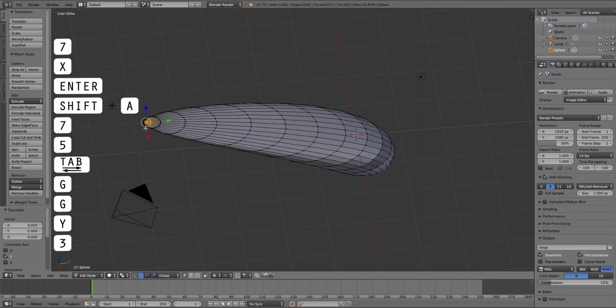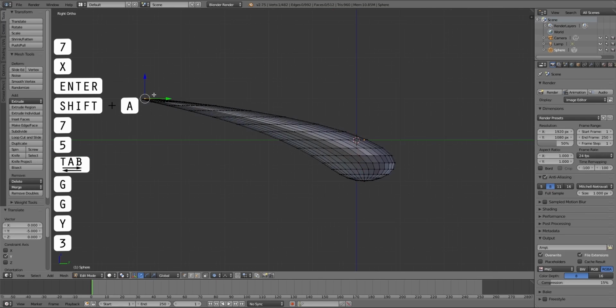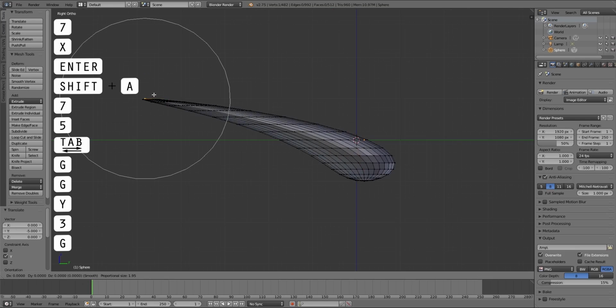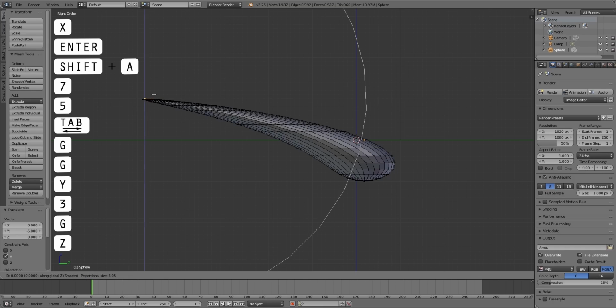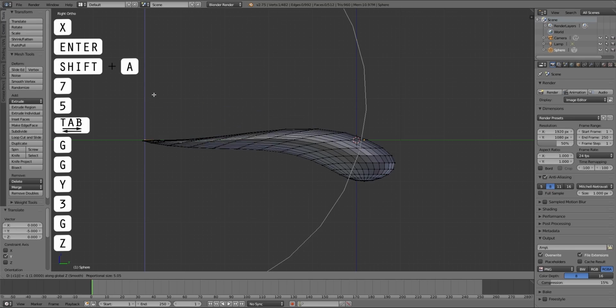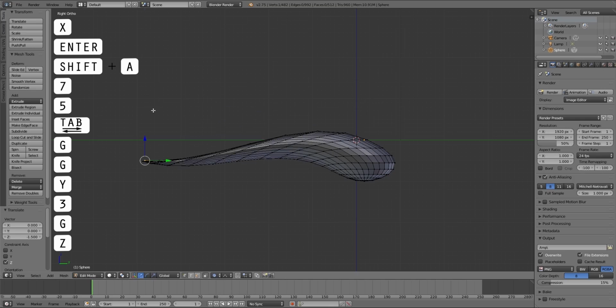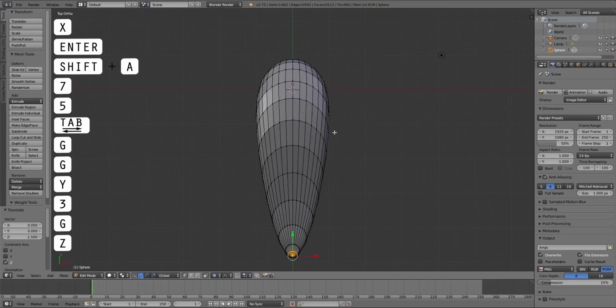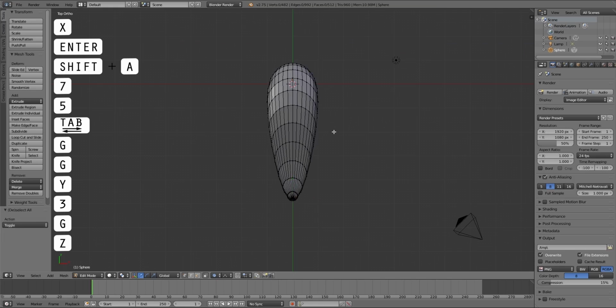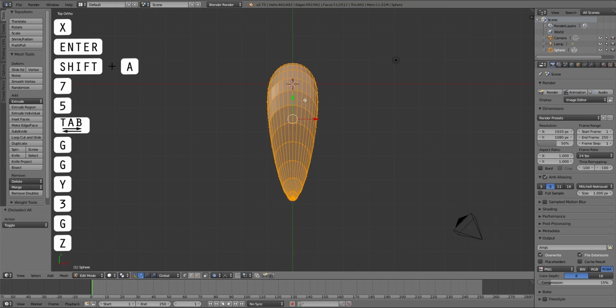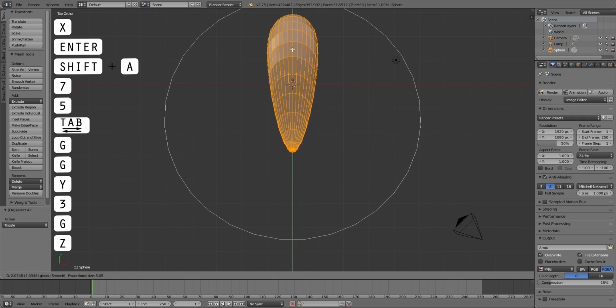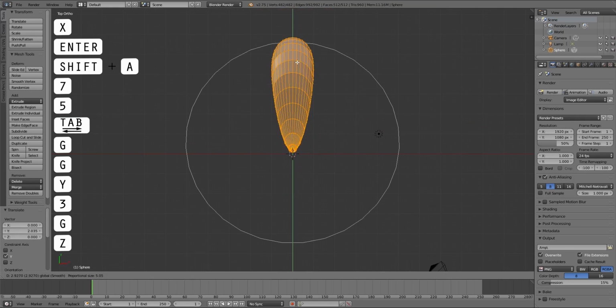And with our vertices still selected, we'll press G again, and we'll change the proportional size to 5 this time, as close as you can to 5. So in my case it's 5.05, and we'll want to move it along the Z-axis this time. And we'll go ahead and type -1.5. Alright, with that done, we've got our first petal, and all we're going to be doing is just duplicating these petals anyway. So we'll go ahead and create the centerpiece of the flower.